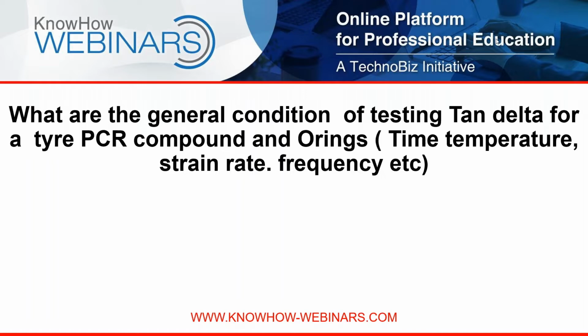Now, say you talk about an O-ring. An O-ring doesn't see any dynamic loads. What an O-ring will see is temperature. So it depends. If the O-ring is applied as an under the hood component in India, sure, room temperature to 150 degrees C. If it works somewhere in Mongolia or North America, then you will go from minus 20 degrees C or minus 40 degrees C to 150 degrees C. Everything depends upon the field of application of your material and component.